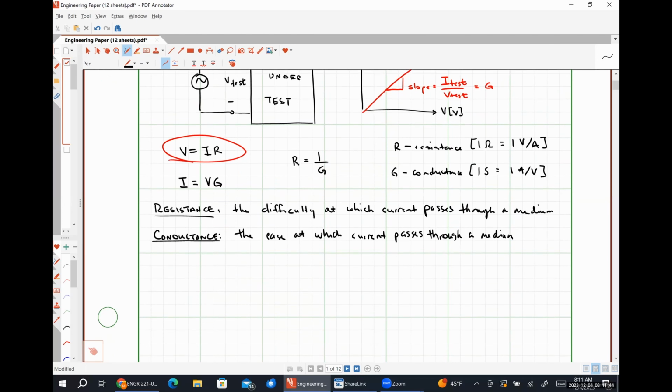So using Ohm's law and our power relationship, we know that P is equal to I times V. This can be alternatively expressed as V squared divided by resistance, or I squared multiplied by resistance, in terms of if we have a resistance given to us, right?